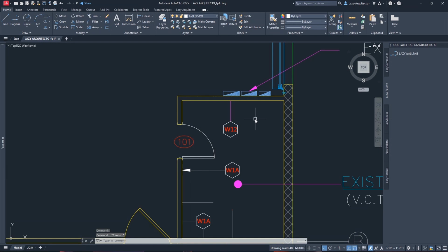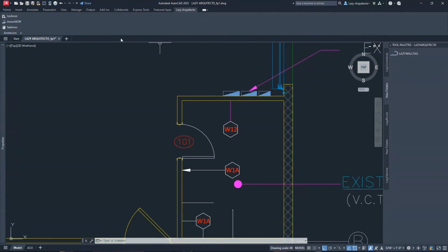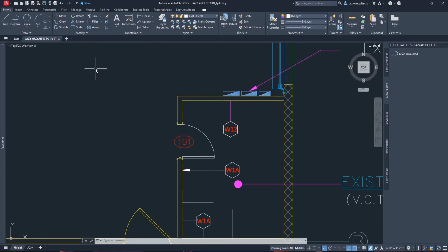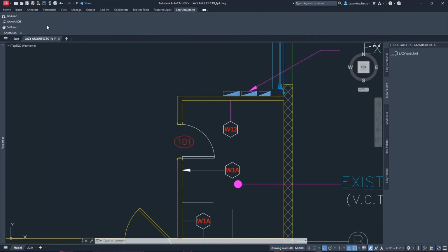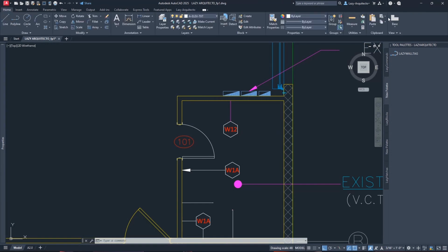All right, so now that we have this macro set up on the right path, let's go to the ribbon now and do the final phase. What I'm trying to do is, instead of wasting time creating from scratch three different commands over here, I'm going to reuse any of these ribbon panels that I like.